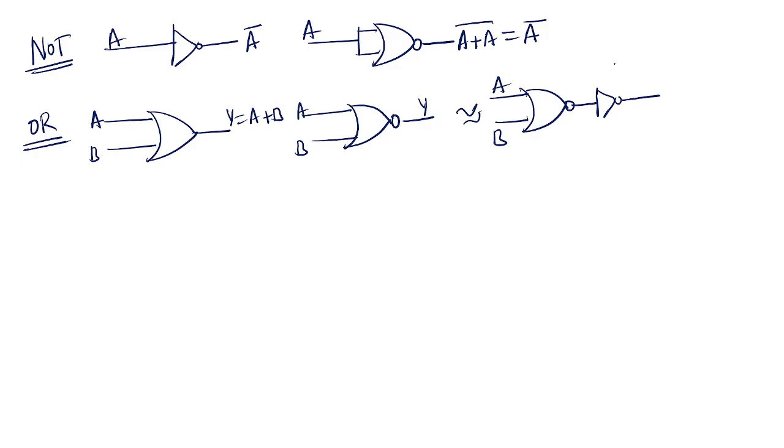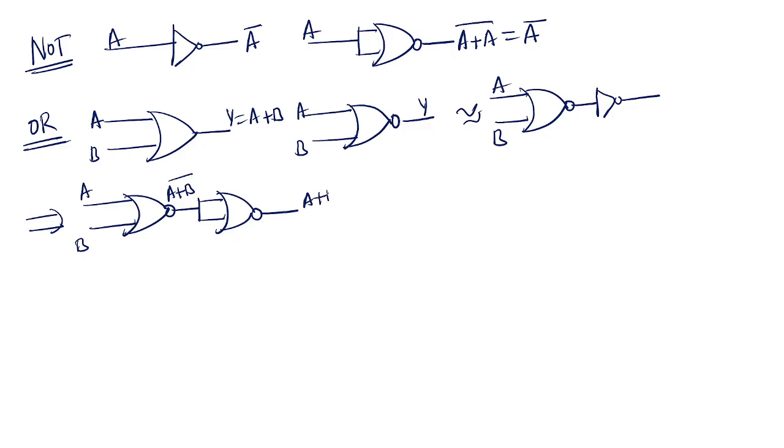Okay. And next, replace all the gates with the respective NOR gates. This is NOR gate and these inputs, this is inverter with inputs tied together. This is NOR gate, A, B, (A+B) whole bar. So this is (A+B) whole bar whole bar, this is A+B. You got the alternate OR gate.